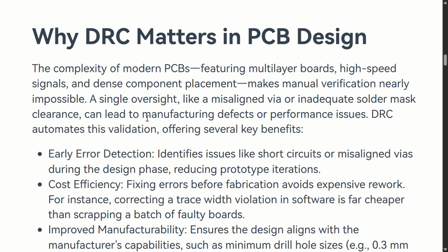In the DRCs they have clearly proposed the minimum spacing; all these rules are already defined. So just follow the DRCs, and even when you manufacture the PCB, nothing will go wrong, because those minimum spacings were proposed by keeping different machinery and equipment in consideration.